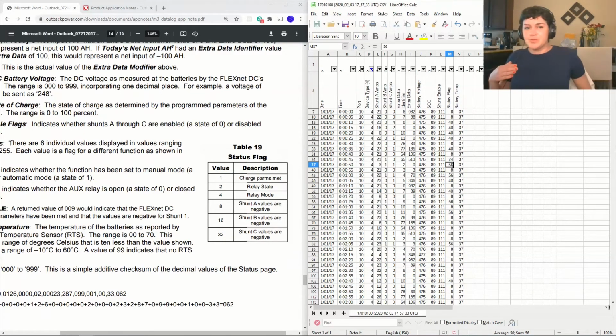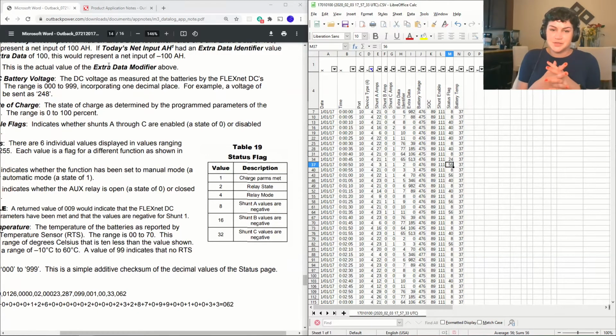This could actually be helpful sometimes, because I've seen people wiring the shunts incorrectly, backwards essentially, and it can give really weird results for state of charge, because you think you're charging, it is charging, and it's actually reading as if it's discharging. So this could be helpful information, understanding, oh okay, what's the flow? How should this look?